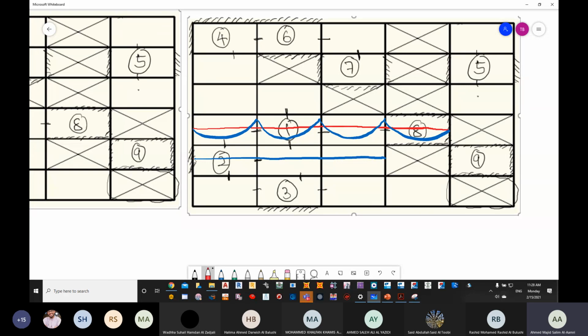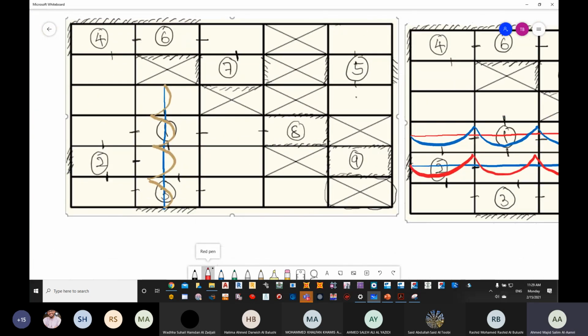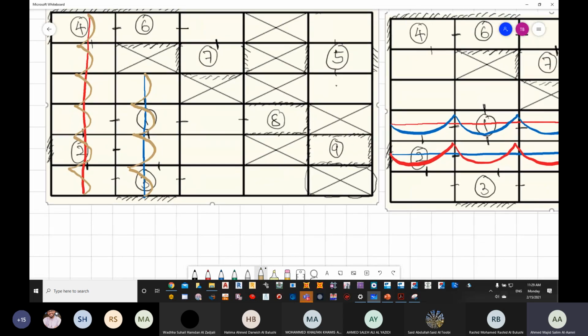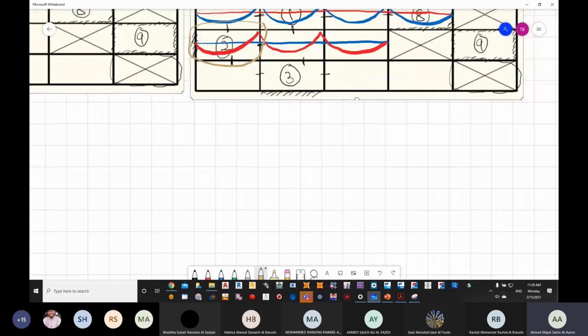you will see this starts from 0, it goes up, it goes down, up, up till reaching 0. On the other side, for 2, if we try to draw the bending moment vertically, you will see that it starts from 0, here, here, here, here, and then it turns back to 0 wherever it's discontinuous. Now you can see 2 is a representation of this bending moment in one direction. It is a representation of this bending moment in the other direction. So you can see it now here.